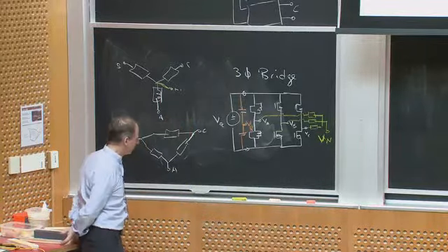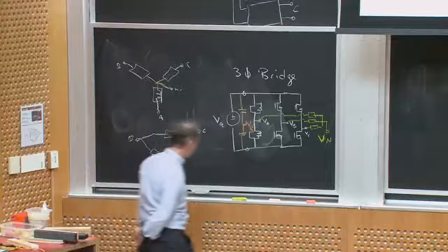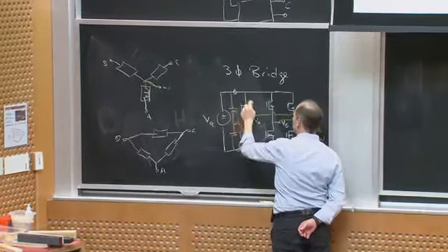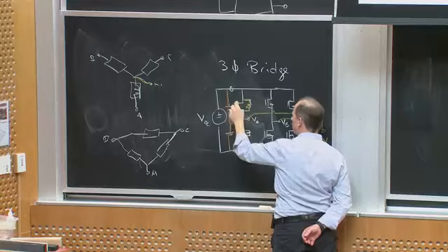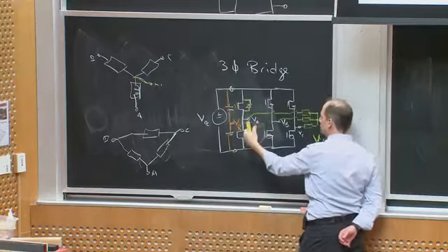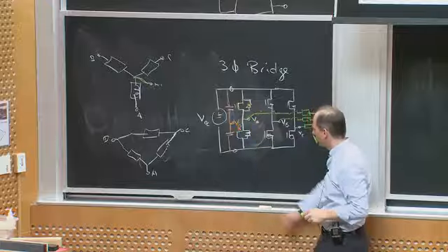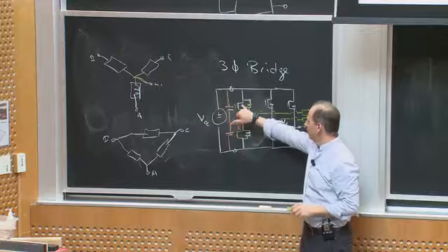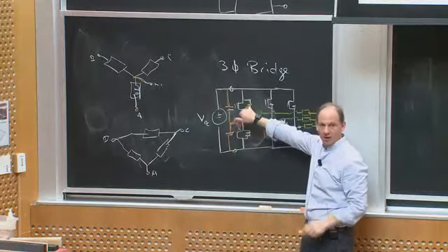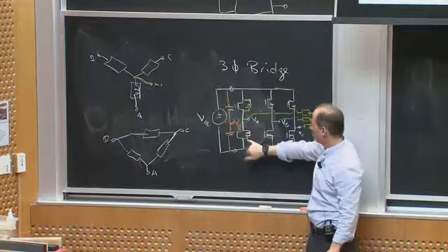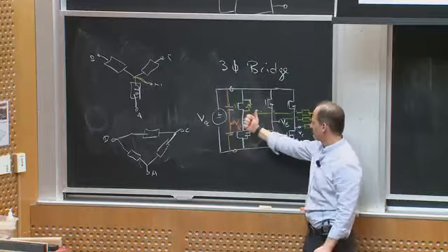Okay, so one thing I wanted to note about this is that I want to pay attention that these devices are, especially if the load's going to be inductive, so I don't actually control instantaneously what the direction of that load current is. I usually have devices with reverse diodes on them, or I use MOSFETs which have it built in, because that way when I turn one device off, I can always guarantee there's a path for the current.